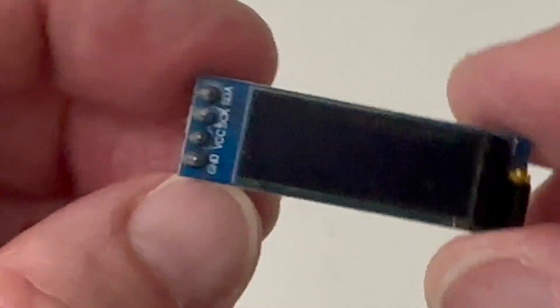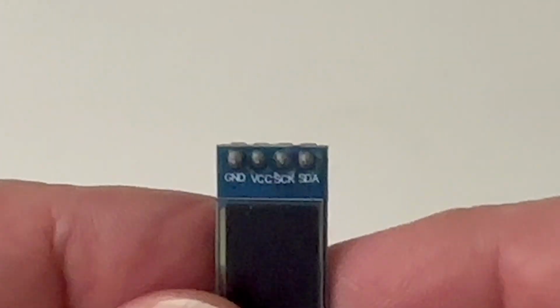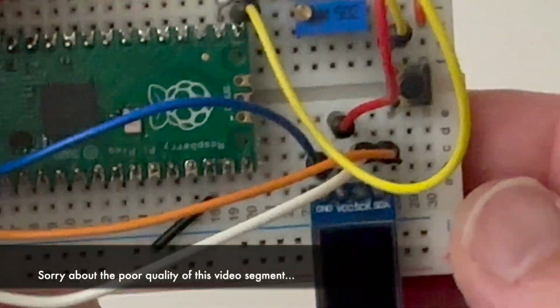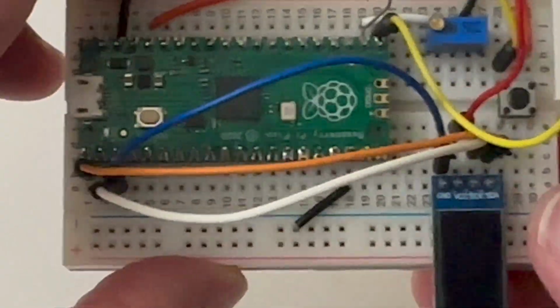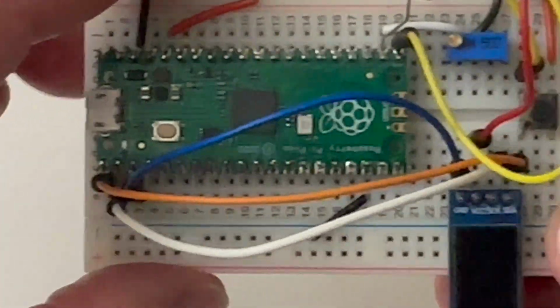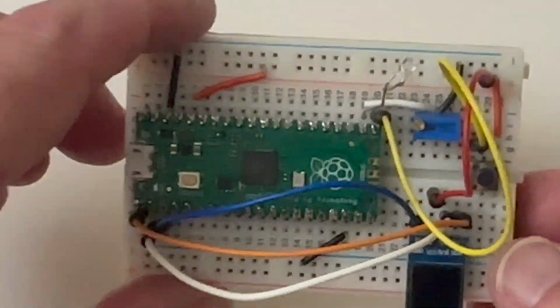First, I added a small display. This is a 128 by 32 OLED display, 0.91 inch. It has 2 pins for the power and 2 pins for the I2C communication protocol, which are connecting to GPIO 0 and 1, which support I2C.